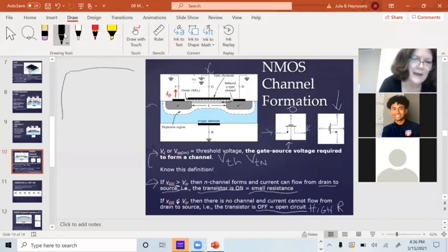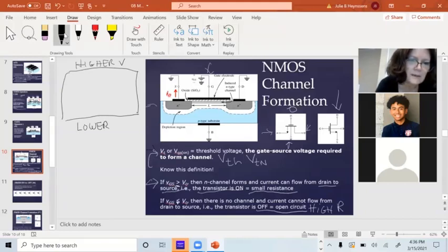You have a schematic. One thing that people normally do is they put the higher voltages at the top and the lower voltages at the bottom. If you draw your schematics like this, other people will have an easier time reading them. And when you look at other people's schematics, they'll make more sense. On this side of the paper, I put the inputs. And over here, I put the outputs.